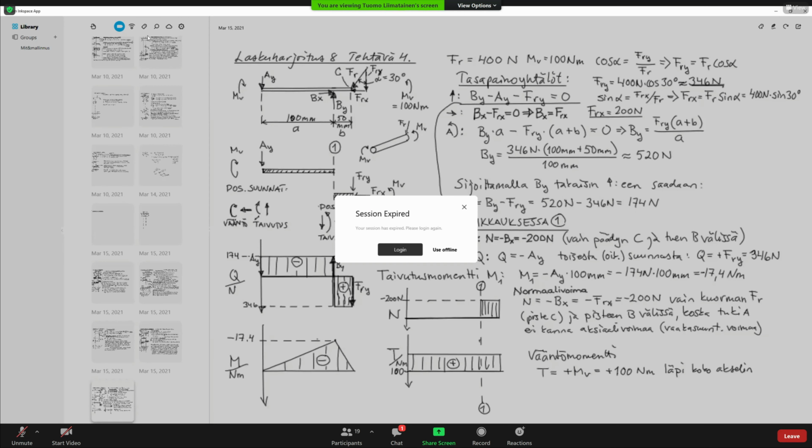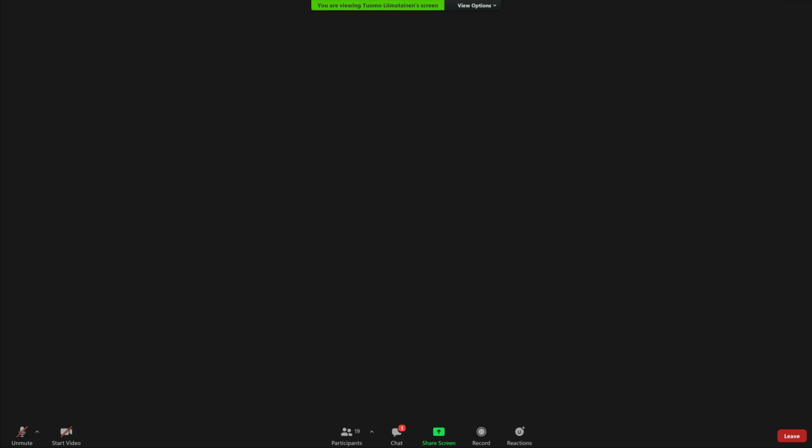So will it be true that with shafts we can just neglect the bending stresses? No, we cannot neglect it. It doesn't mean that. But it means that the bending from gravity load in a rotating shaft is always fully reversed. It means that there's no mean stress from the gravity load in a rotating shaft. So it's only applicable for mean stress, not to all stresses. For example, if we are calculating for von Mises, then we are taking into account the bending as well.